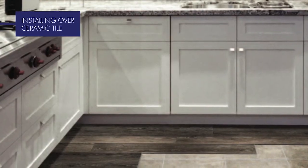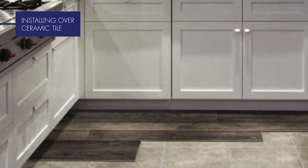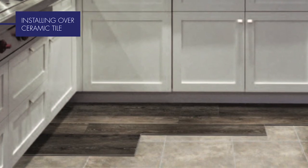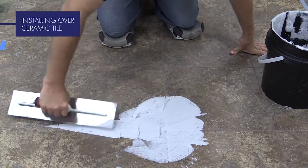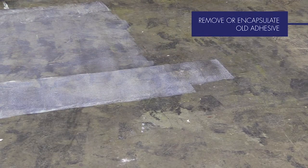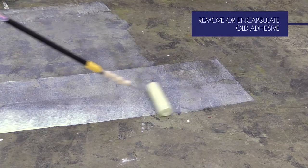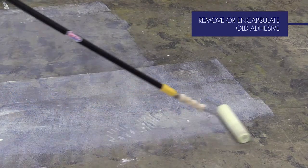When installing over ceramic tile in residential applications, filling grout lines is not required so long as subfloor flatness guidelines are followed. In commercial applications over ceramic, grout lines must be filled. When carpet or vinyl has been removed, old adhesives must be scraped up, skim-coated, or encapsulated, and left so no ridges or puddles are evident and what remains is a smooth, thin film.